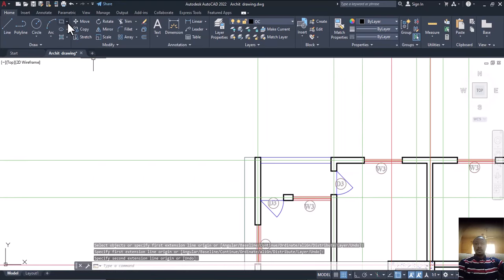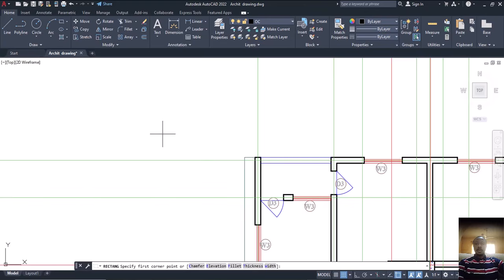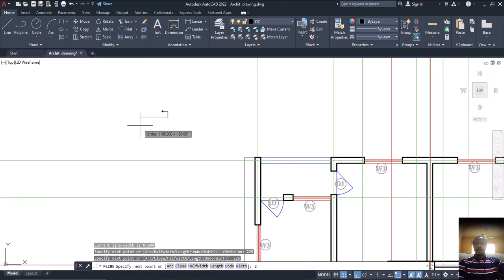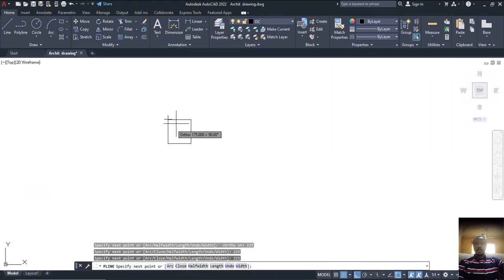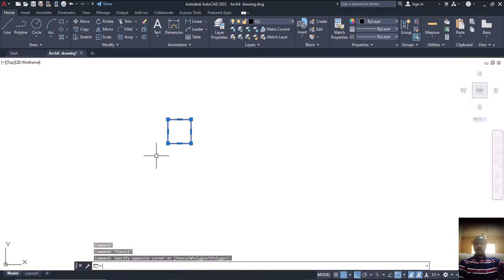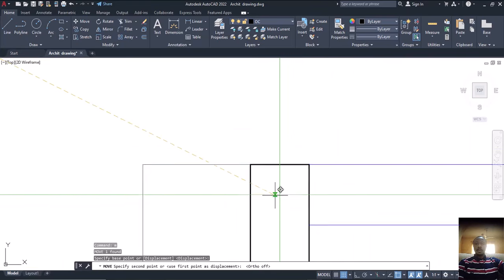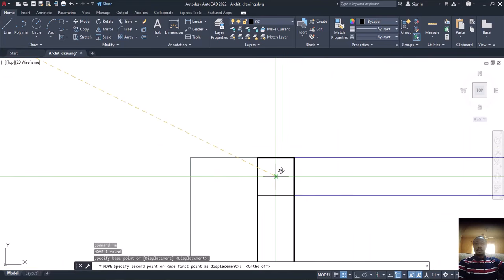All right. So I'll come here now. Let me use my polyline. I'll come here. Let me put my straight. Then 225, enter. Then 225, enter and come here. 225. Enter and finally I close it up here. If I click on it, it's showing me. It's okay. I'll select this one now, enter. From the point here, I will move straight to the intersection point, which is at this place now. I'll click on it.